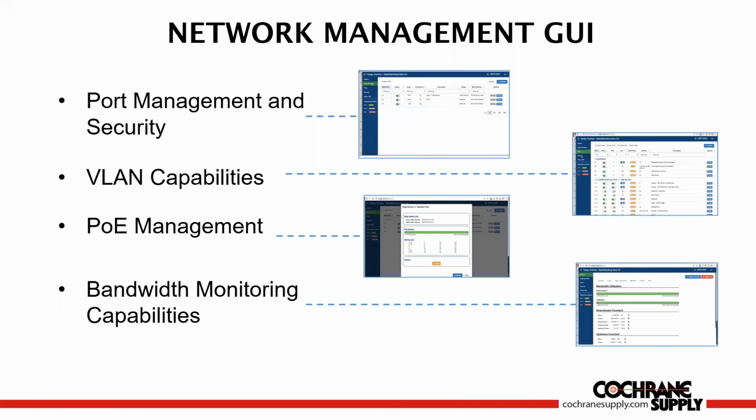So if you've got an integration project with lighting controls, HVAC, security, and let's just say the generators are also integrated, then you've got 4 separate technologies there. You may want to separate all those technologies on the network and then go and set up sub VLANs within each technology, right? So the HVAC, you may want to separate all the air handlers from all of the AV boxes, or do it floor by floor. But you want those VLAN capabilities so that you're able to do that.